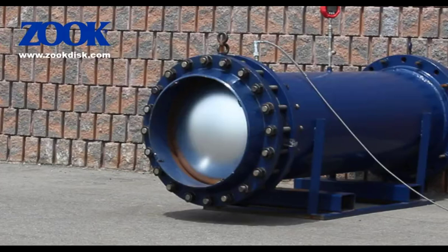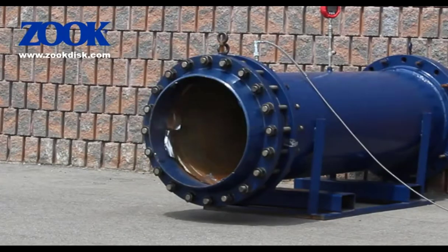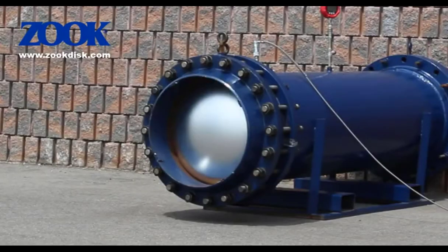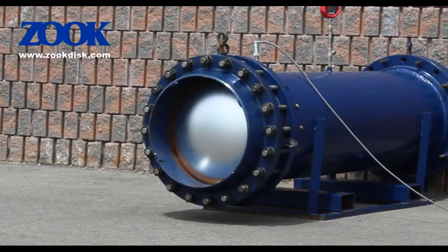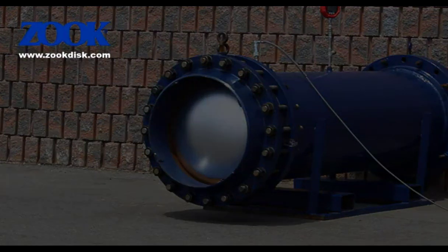Here you can see a rupture disk mounted to the end of a chamber, which is sealed at one end and a rupture disk mounted on the other. Pressure is introduced into the chamber and the disc bursts or opens when the pressure differential reaches the set point of the disc. Differential pressure simply means the pressure on one side of the disc is higher or lower than the other. If you pressurise both sides of the disc equally, nothing would actually happen.